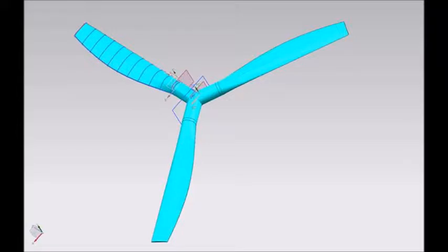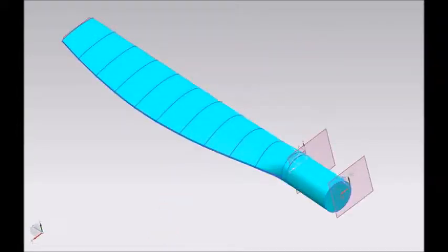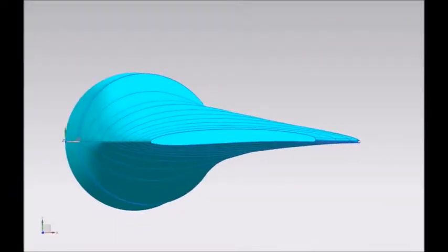This is one of the 14 propellers on the X-57 aircraft. To simplify things, we can just look at one of the 3 blades. Since my analysis is only 2-dimensional, the blade then gets divided up into 11 cross-sections, or airfoils, to be analyzed separately. This is important because they're not all the same size.